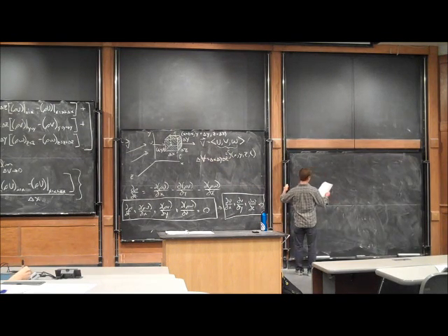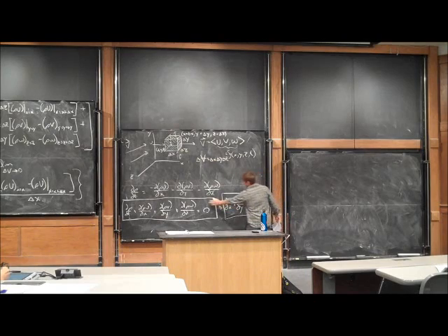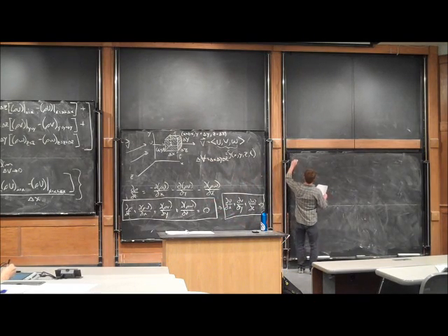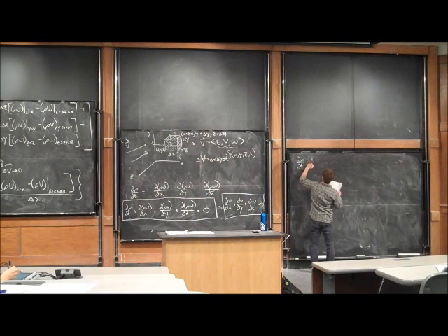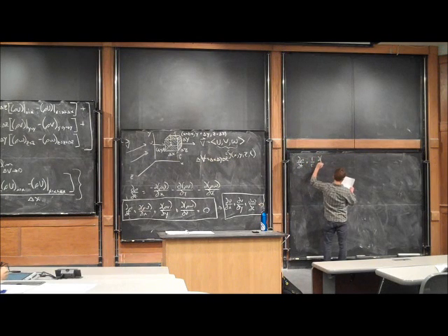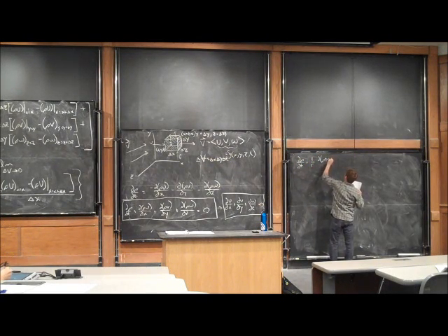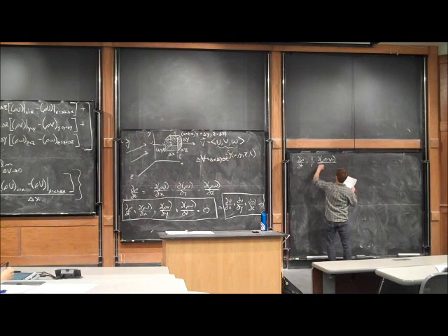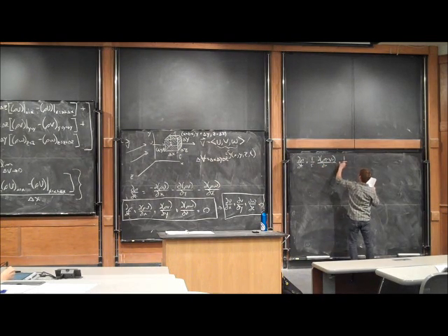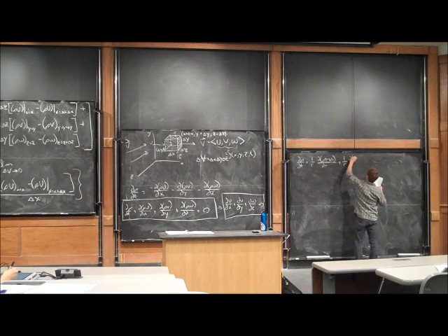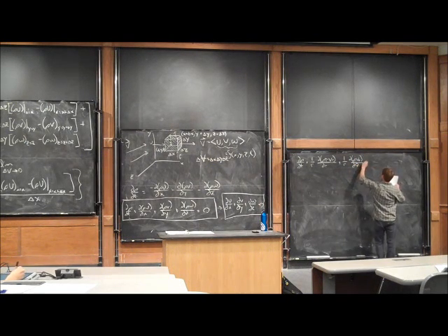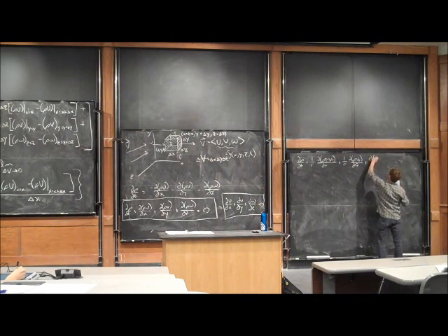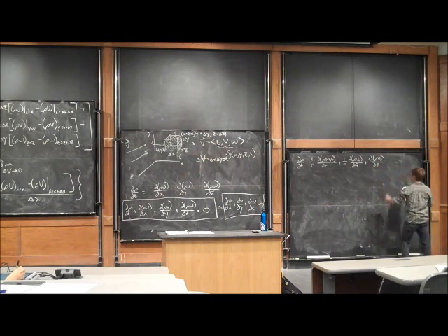But if you look it up in the e-book, this form of the conservation of mass equation becomes ∂ρ/∂t plus 1/r ∂(ρ r v_r)/∂r plus 1/r ∂(ρ v_θ)/∂θ plus ∂(ρ v_z)/∂z. And in this coordinate system, that's all equal to 0.